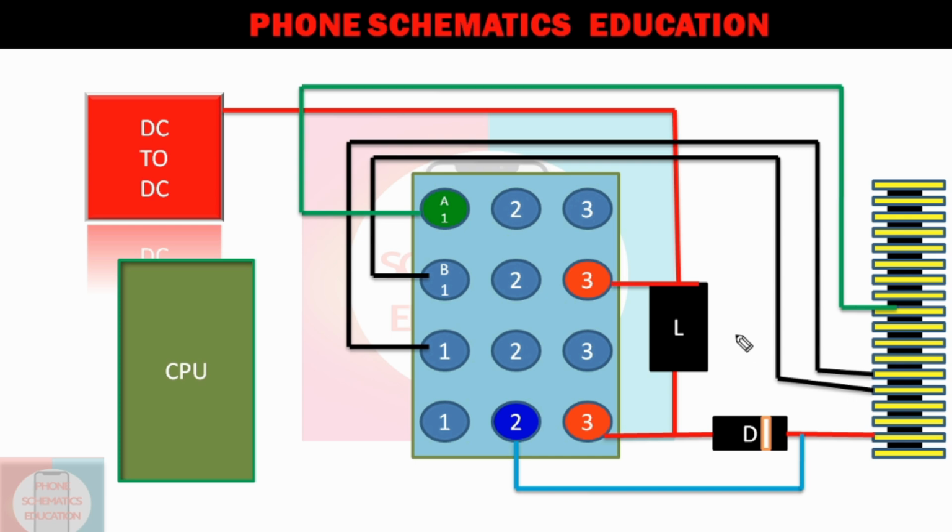But on the LCD section, in 90% of phones, if your light section is damaged for any reason, like water damage, waterlogging, shorting, or an open line, you will see the graphics, or faint graphics, when you look carefully with the help of a torch. But in 10% of cases even LCD phones do not show the graphics.